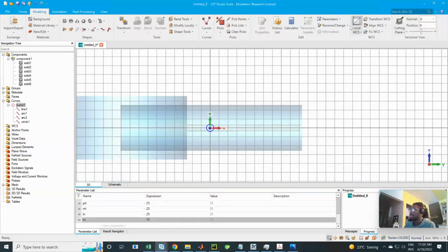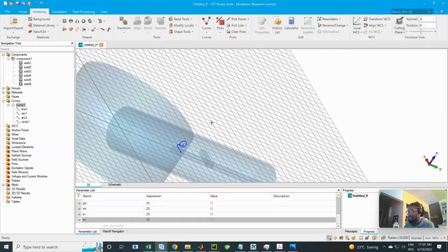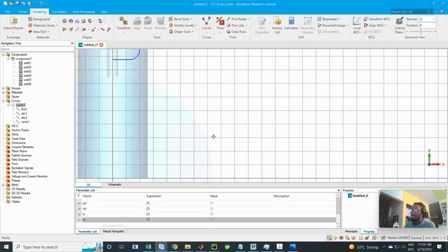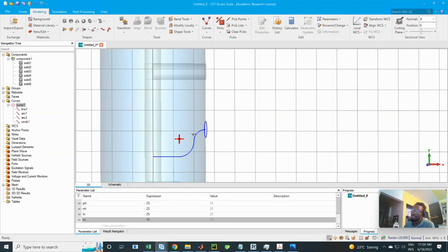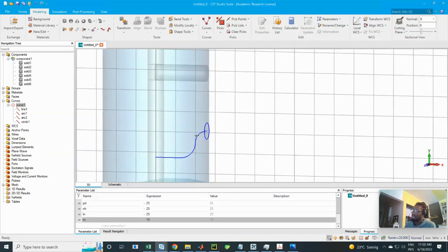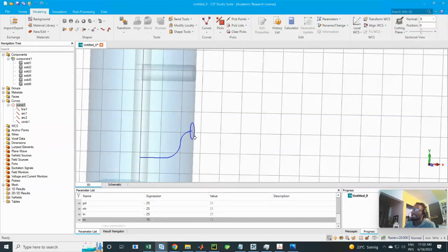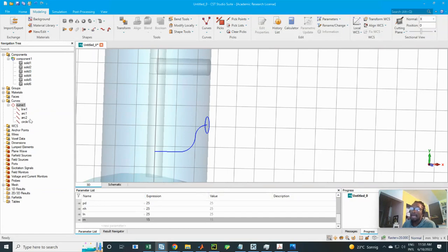So I've gotten my circle and I'm creating it from the local coordinate system, and voila, I have my circle there ready to be swept. Okay, not actually off their feet, along this part. So for that, I could do one of many things. I could either click on the circle, then click on sweep curve.